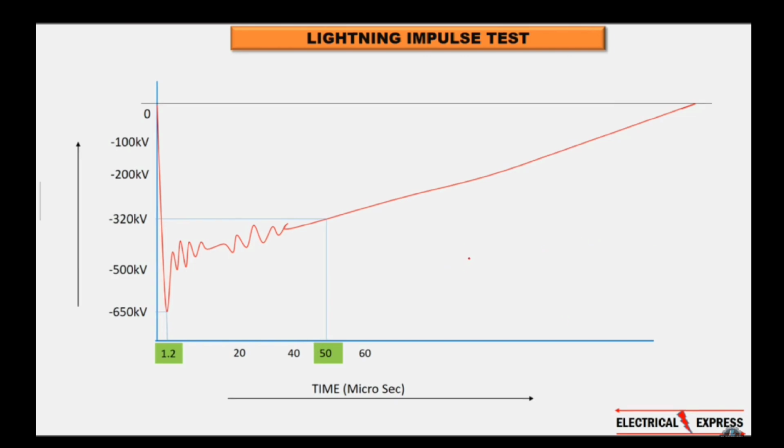What does applying negative voltage mean? That, like we apply high voltage here, for example, 650 kilovolts, 1050 kilovolts, we apply negative polarity voltage, like minus, because whatever charged particles, ions, surrounding mediums, whatever particles are there in the air, all are negatively charged. So if we apply positive voltage, then positive and negative ions can get ionized here, and there are chances of flashover in the bushing. That is why we apply negative voltage, so that negative and negative get repelled, and whatever flashover or collapse voltage chances are there, they do not happen.